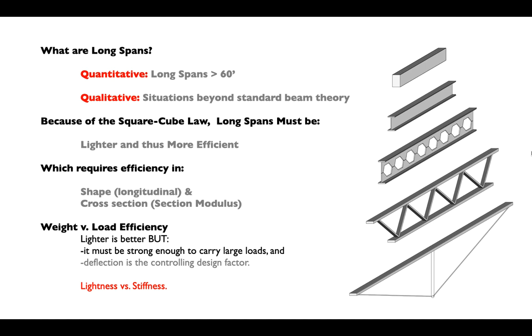And so note that now we have maybe an even greater depth with maybe even less weight, right? This is why a truss is such an effective long span element, because it's basically making an I-beam with a web that weighs almost nothing, right? Putting almost all of its material into the two flanges.